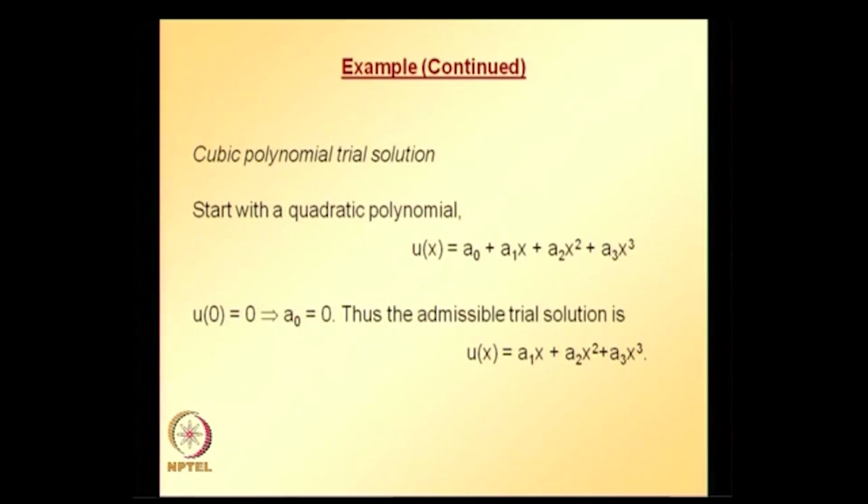The first step is to multiply the given differential equation with the variation of the quantity you are interested in, integrate over the problem domain, and apply integration by parts to reduce the order of the highest derivative appearing in the expression. Then apply the essential boundary condition, that is, wherever essential boundary conditions are prescribed, the variation of u is equal to 0.